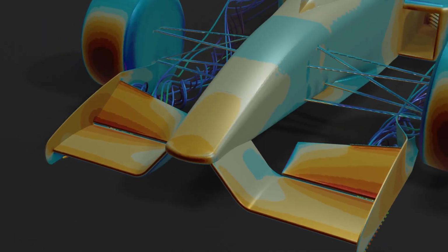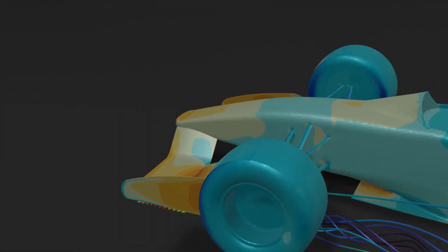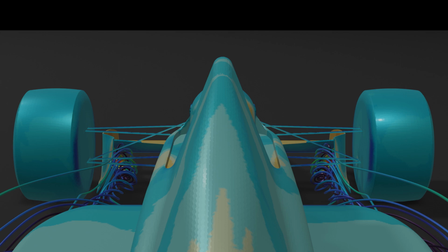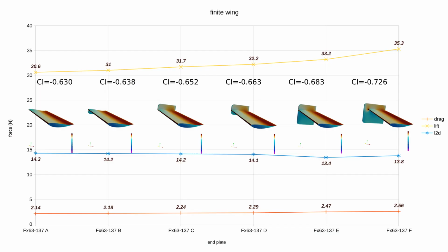Related to this problem of the high nose is the discontinuity of the finite wing. The dihedral aspect of the wing mitigates this slightly, but without the ground effects, in effect, there are 2 finite wings rather than 1 at the front. Basically, it doubles the discontinuities and the resultant inefficiencies. Basically, we're talking about a 30% decrease in efficiency per discontinuity.